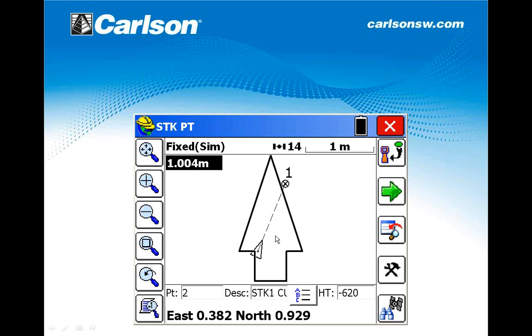This heading we compute right now is based on the last track you did, like 3-4 meters before getting to the proximity cycle, right? So those 3-4 meters are important, in the sense that you should be heading to the point, approaching the point, and not doing big changes in your trajectory, okay? So when we compute an average azimuth on approaching the point, that is your reference for the final refinement of the point.